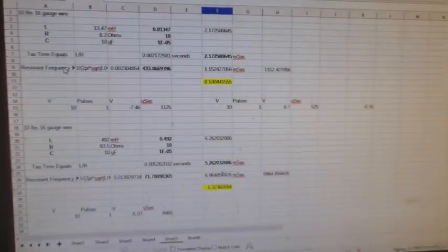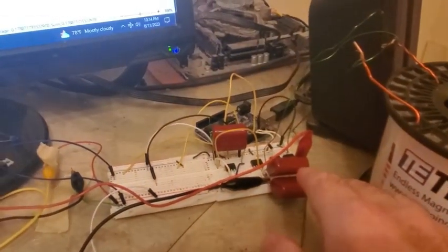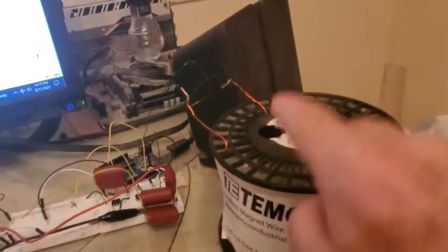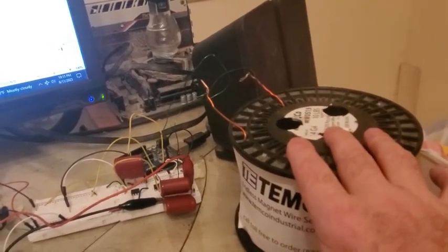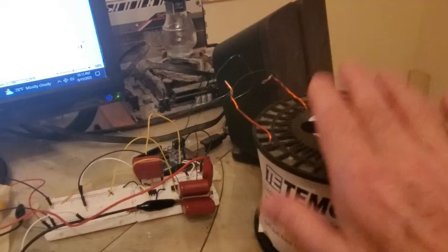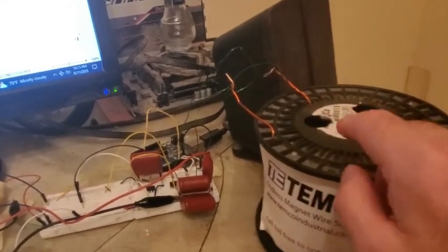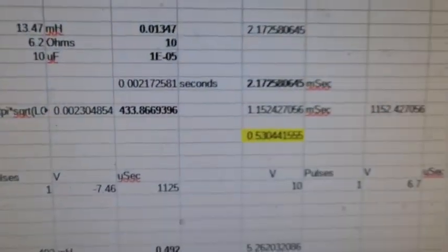The resonant frequency is how fast your discharge is. And so the cap discharges at the resonant frequency. And so that rate of change is determining how fast the magnetic flux is changing in your inductor, and how fast and how strong a field and how fast it is changing per Faraday's law of inductance is how big of an EMF you get.